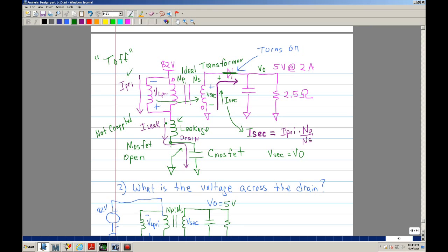Okay. So what it does, some of the current actually goes and flows through the capacitor, and you can call it a displacement current. Okay. And this current actually charges the capacitor up, and the flux in the inductor goes to 0, but then this is charged, so then it recreates the flux back on the leakage inductor, and it goes back and forth, and what you get is you get ringing. Okay, you'll get a decaying ring. So that's where this leakage current is going through.